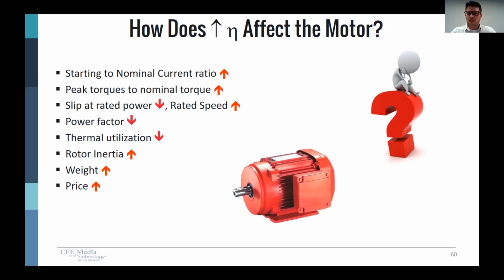So different things are affected, but remember, back in the first section when we were talking about the relative potential difference we can make in changing components and saving energy, I told you that using a high efficiency motor was something like 10% or so, using the VFD we could gain 30%, and in mechanics we could stand to gain roughly 60%. Well, if using an induction motor of higher efficiency or a premium efficiency I can only save 10% of the overall energy of my system, is that worth it? Is it worth doing that?